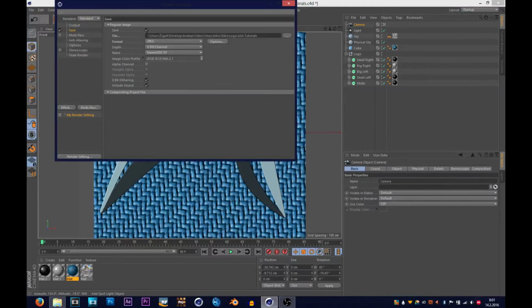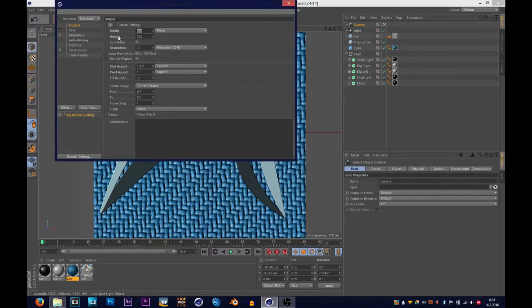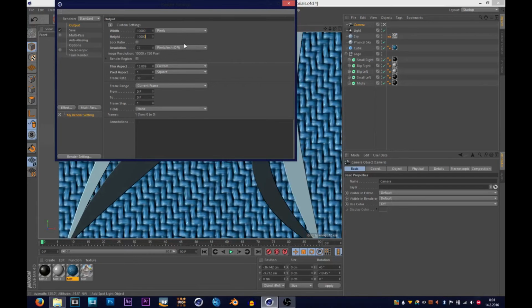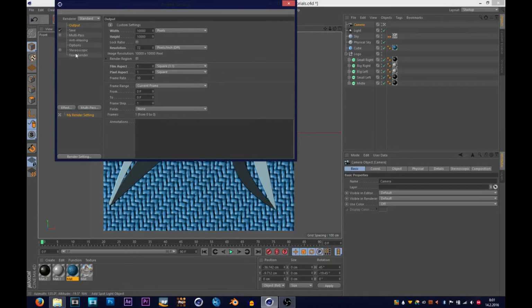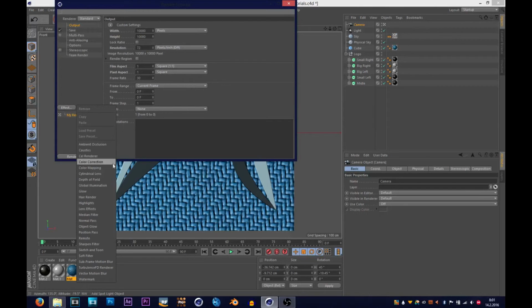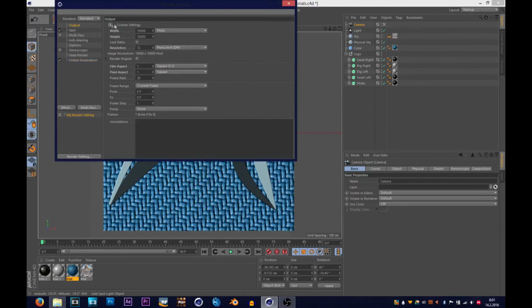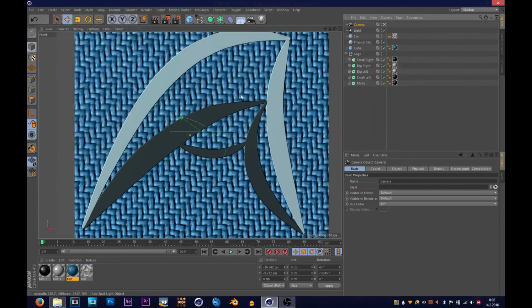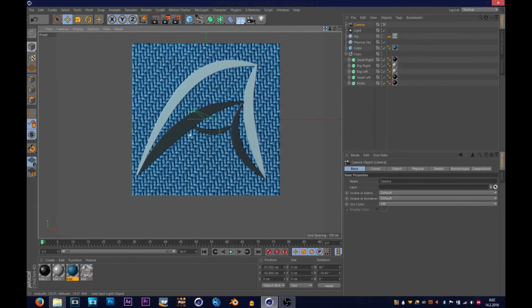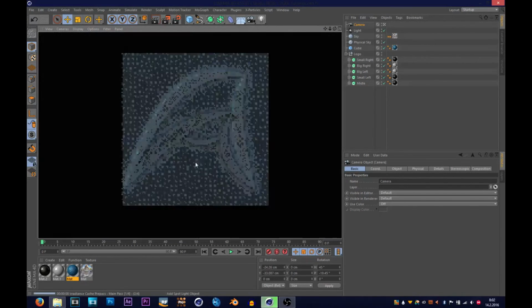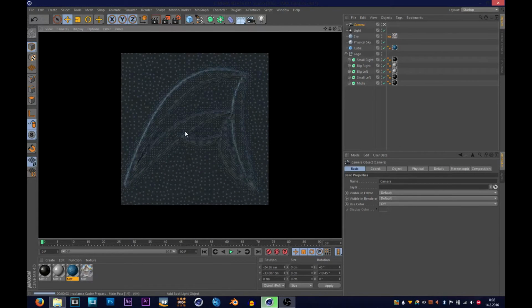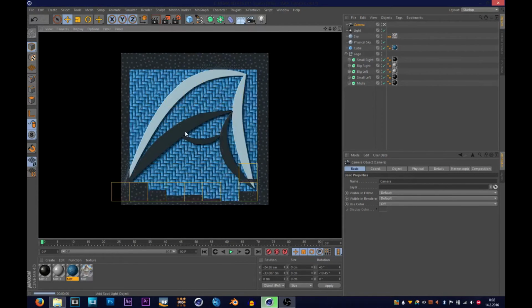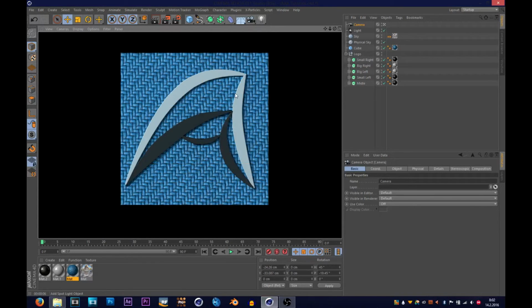And now we go to output. If you want to have a really big photo, you just press 10,000 by 10,000, and it will be really big. Make global illumination, it's very important. I make this bigger because it renders a very long time if I have 10,000 by 10,000. So it takes a little bit, but don't worry, the results are very much better.